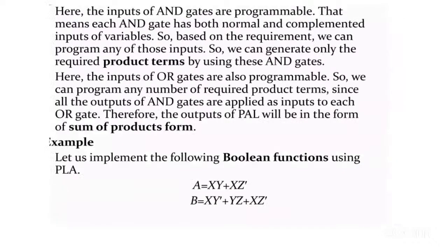Here the inputs of AND gates are programmable. That means each AND gate has both normal and complemented inputs of variables. So based on the requirement, we can program any of those inputs. So we can generate only the required product terms by using these AND gates.